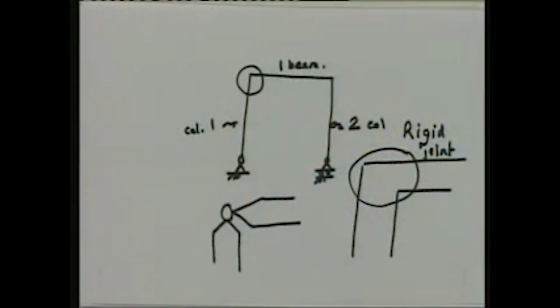Let's come back to the problem that I was discussing a little bit earlier. Look at this. This is the plane frame. How do I find out the static indeterminacy of the plane frame? Can I use m plus r minus 2j? What does that mean?